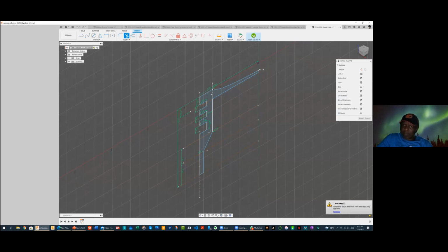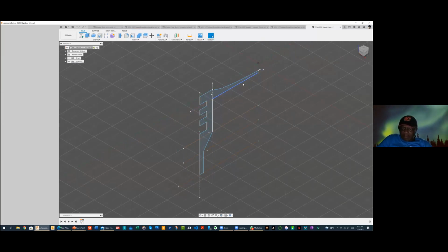Okay, finish sketch. So you can see a clear picture of what we want to revolve. We want to revolve this. You see, it's very reassuring when you see, before you go to revolving, make sure that the object you want to revolve is a closed circuit. I cannot overemphasize that. So we now say create revolve.